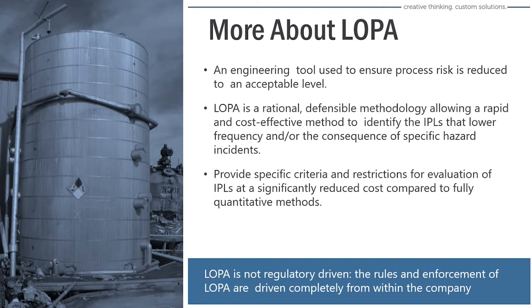By adding LOPA to that PHA, I think it'll add some additional insight into some of the controls you may have in place. Some of the assumptions you may have been relying on for years may be tested, and it's a great way to get a fresh look at a process that has been around a long time and that people are getting kind of complacent about.